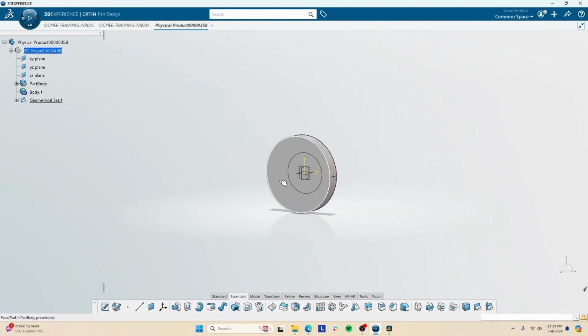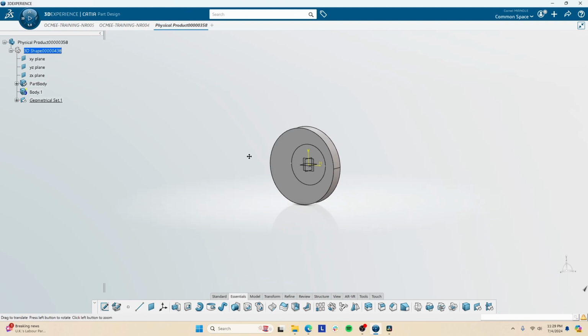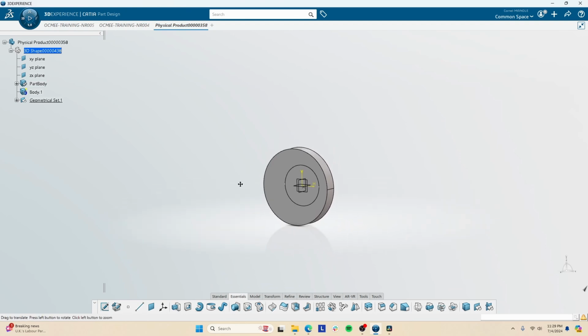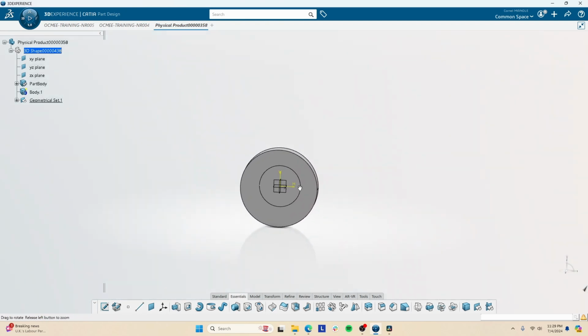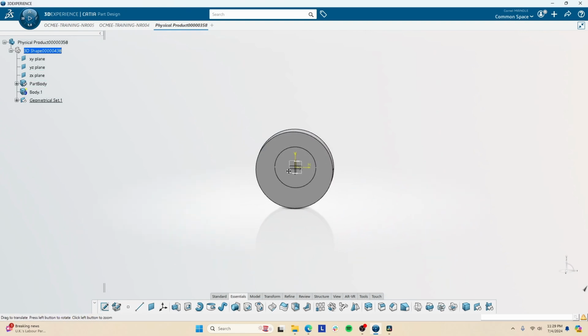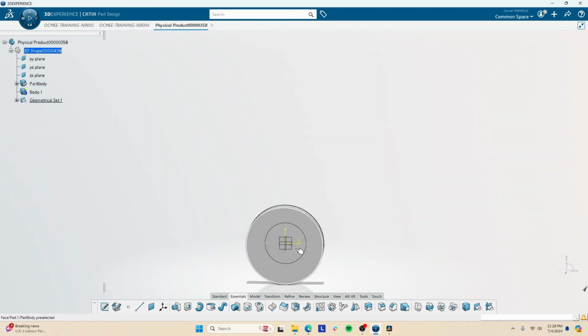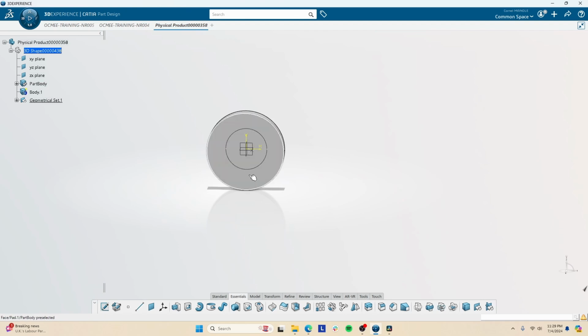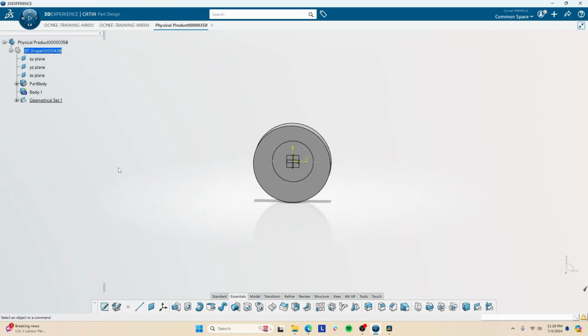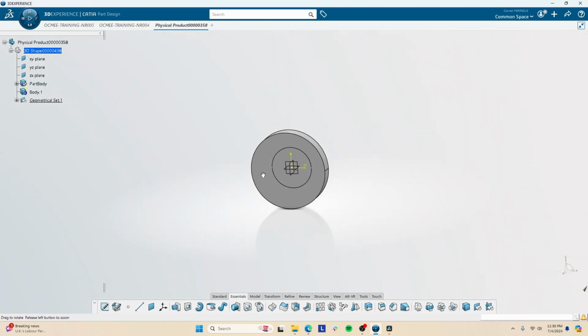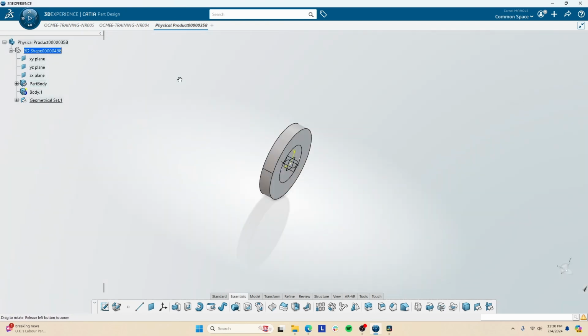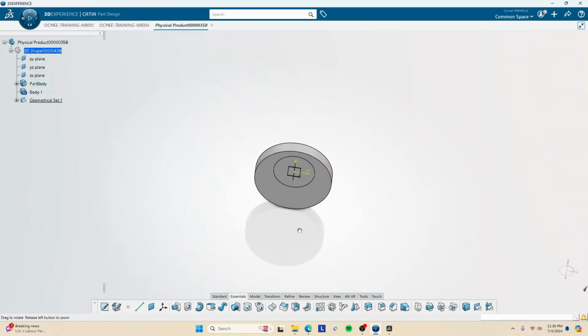In place of your clicks, you could also use the control button. So I'm pressing on the scroll wheel, and in place of my clicks, I press the control button real quick. There you go, changes into zoom mode. And if I press the scroll wheel and I just hold down control, then it will rotate. I could also click with my scroll wheel to, I'll call it instant pan. So if I'm over here and I instant pan to the center, and then I hold that down and rotate, then for the most part, it'll behave as you expect it to.